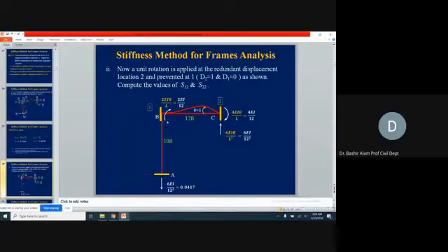From member BC. It was downward. At B, it will become upward, and then it is going to be balanced by this downward 6EI over 12 square. Here, what will be the horizontal force? We don't have any horizontal force here from member AB, so that 0 is going to travel here. So it means horizontal here is equal to 0.